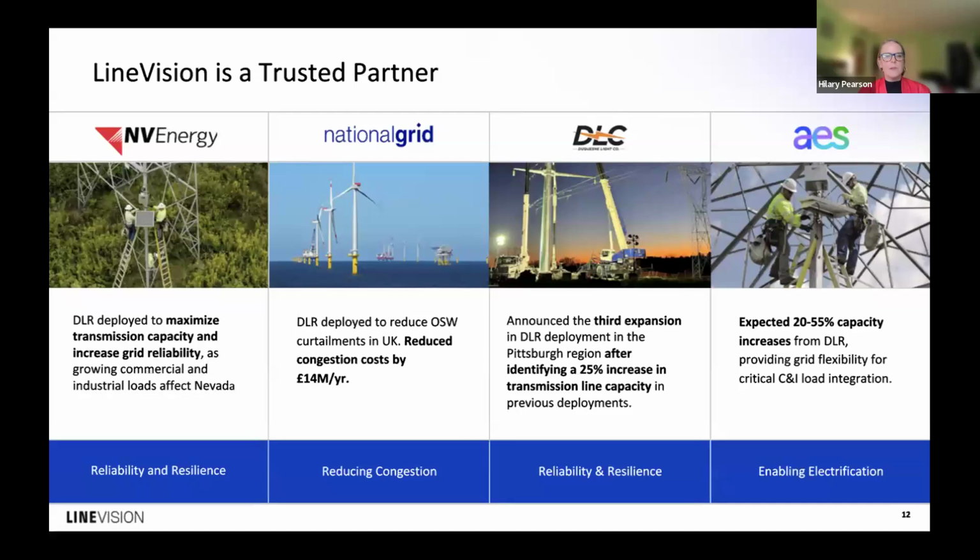what that means, there was a study done in Texas over 15 years ago that found that just a 10% increase in capacity on a line is enough to eliminate virtually all congestion on that line. And when you're able to eliminate that congestion, it just creates that much more headroom for electrons to flow, again, depending on the season. Next slide, please.